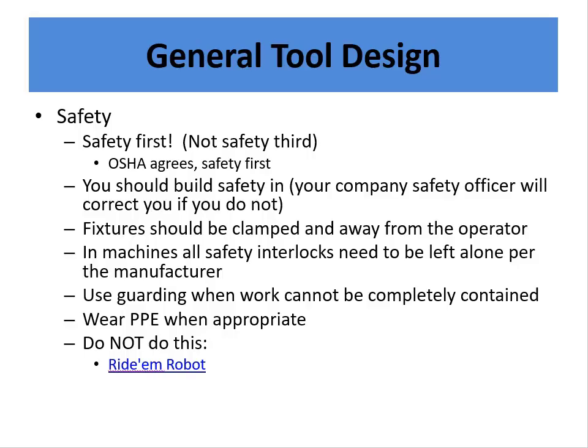So if you ever find yourself in a situation at work where you are having to defeat safety interlocks in a machine that are designed by the manufacturer or specified by your company to be there, you're probably doing it wrong. So, if you ever find yourself in that situation, you should default to, hey, we shouldn't be doing this. If you're defeating interlocks in a machine, then just stop right there. You should probably call somebody or do something to make sure that situation is not left on.